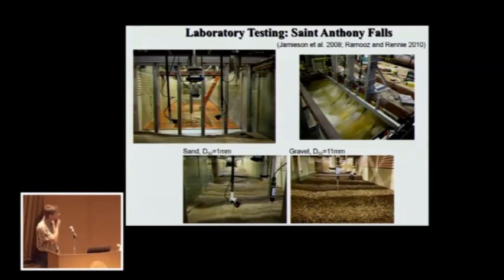So the next phase was to go into the lab. I went to St. Anthony Falls in 2006 and did some measurements in both sand and in gravel using both a 1200 kilohertz ADCP and a 600 kilohertz ADCP. The nice thing about the St. Anthony Falls lab is they'd set up bed load traps, and so I was able to get good measurements of the actual transport rate.